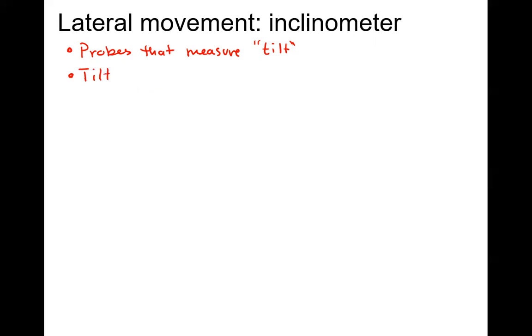So if you think about it, tilt. If I know that I'm traveling at this degree and I'm going 50 feet, then I can measure how far off the track I've actually gone. So tilt plus depth is equal to lateral deflection.